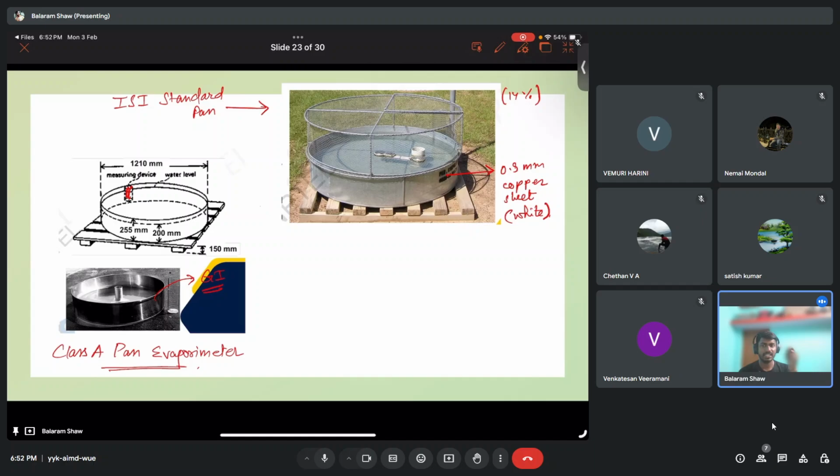So let's say whatever large water bodies or lakes we have, we want to know the evaporation from that, right? So what we'll do is just multiply the pan coefficient based on what pan instrument we are using, and then we'll get the evaporation that is happening from the lake. And there comes the pan coefficient, or we write it as Cp.